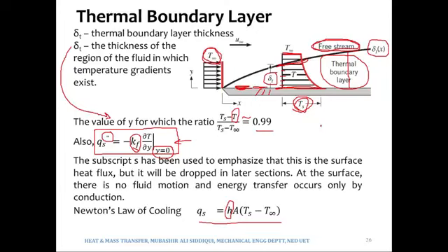And as per our previous discussion, since the velocity is higher, it will end up in higher convection heat transfer. So what did we change? We did not change any material. We did not change any material's property. All we changed was the velocity of the fluid. The velocity is not really a material's property, right? So we only changed the velocity of the fluid, and we changed the convection heat transfer rate. It depends upon other parameters as well, such as the k of the fluid. The convection heat transfer rate depends upon the k of the fluid.